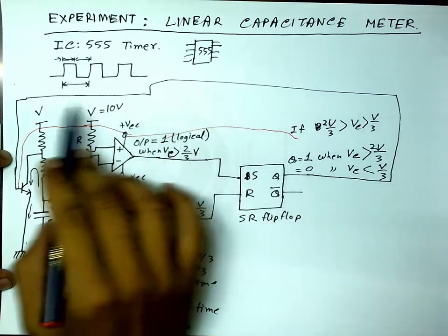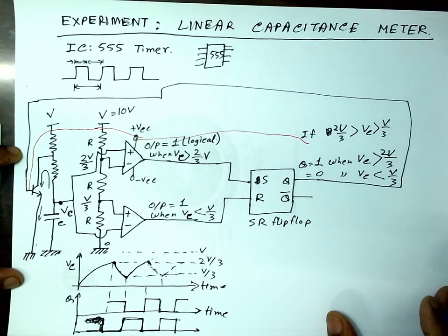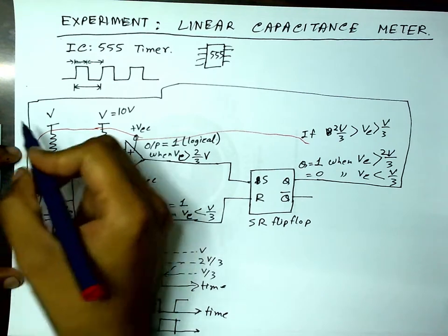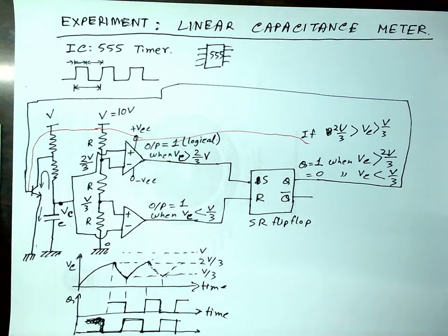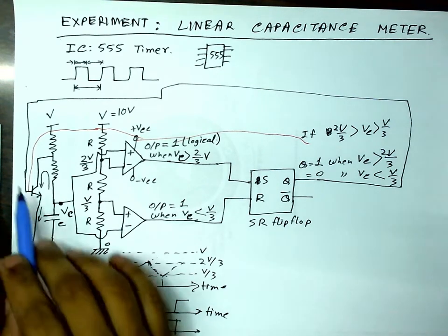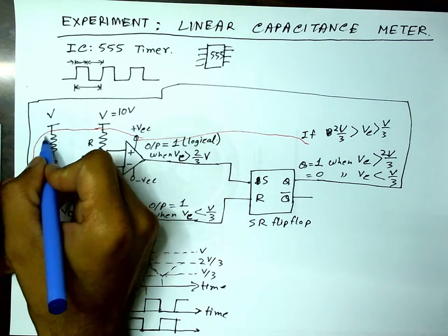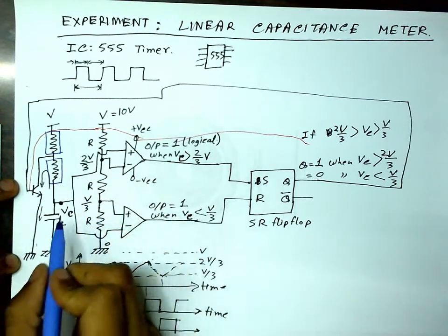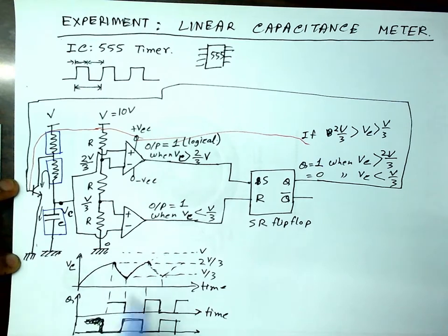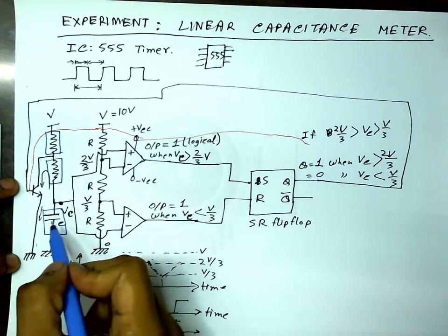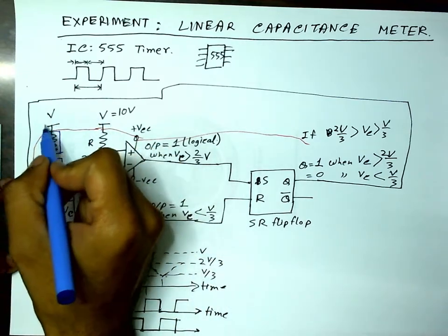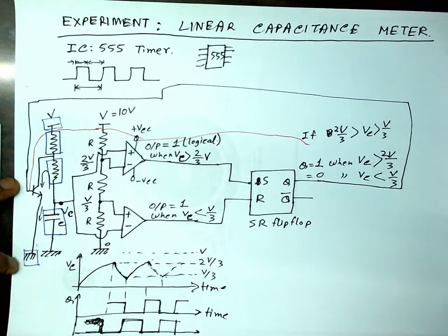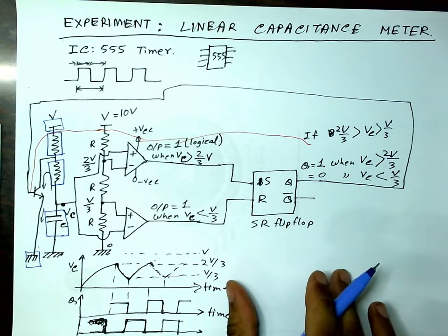So okay, this is the internal diagram of the IC555 timer, and we have access to a few. Okay, let me use a different color. This red is nothing. So this resistance, this capacitance, okay, these are outside the chip. These you connect through the pins, they are outside the chip. This, obviously this voltage supplies, this should be also accessible from outside as a chip. The grounding point should be accessible as a chip.